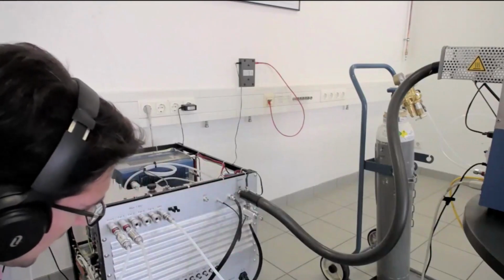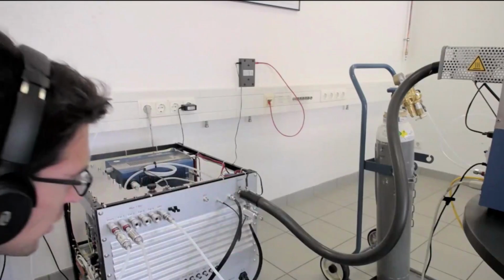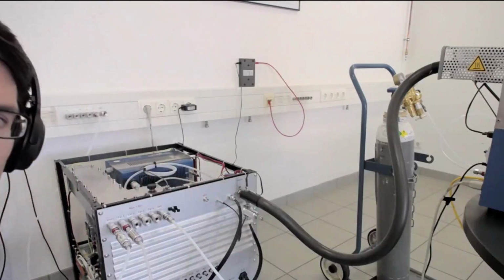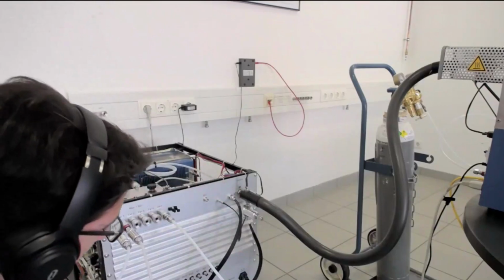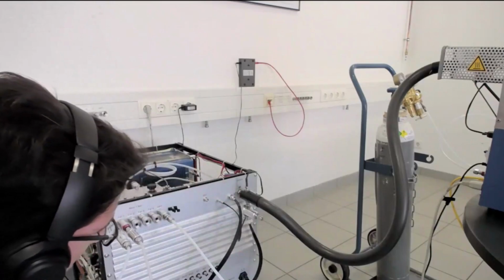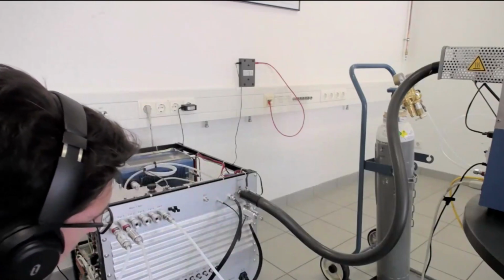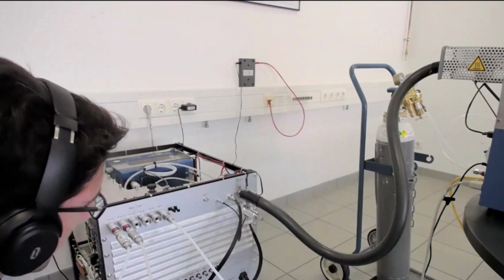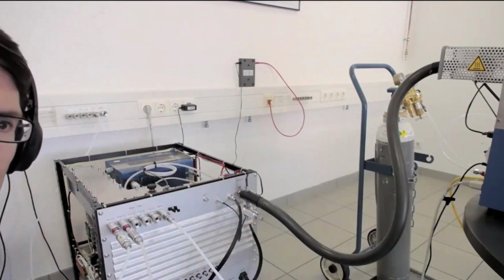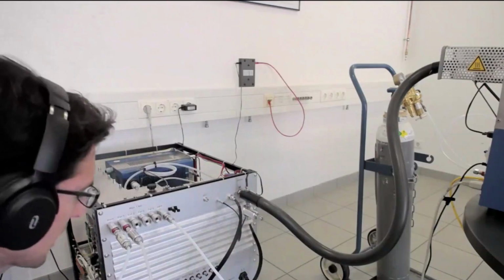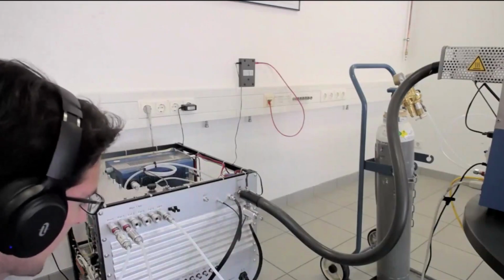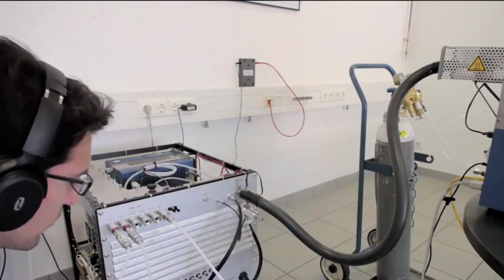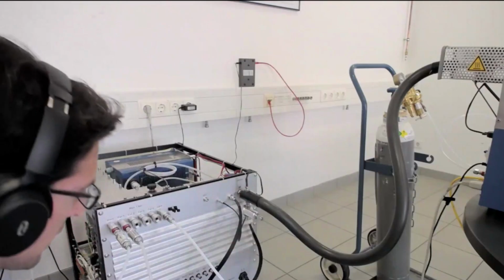We have the possibility of analog input and output signals, which means there are 4 ports for analog out and 4 ports for analog in, where you can either feed signals into the instrument or take them out as a voltage reference, which is typically set to -10 to 10 volts, but can be adjusted to the requirements on the test bench.